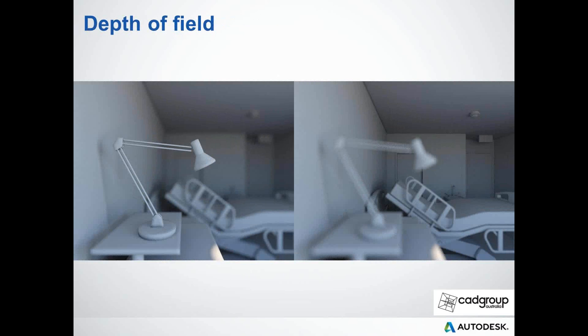Also, if you want to create that photoreal effect, there's a tool called depth of field. So within the cameras in 3ds Max Design, you can adjust your depth of field. Whether you want to focus on something detailed in the foreground or something detailed in the background, the 3ds Max Design cameras allow you to set this focal length.